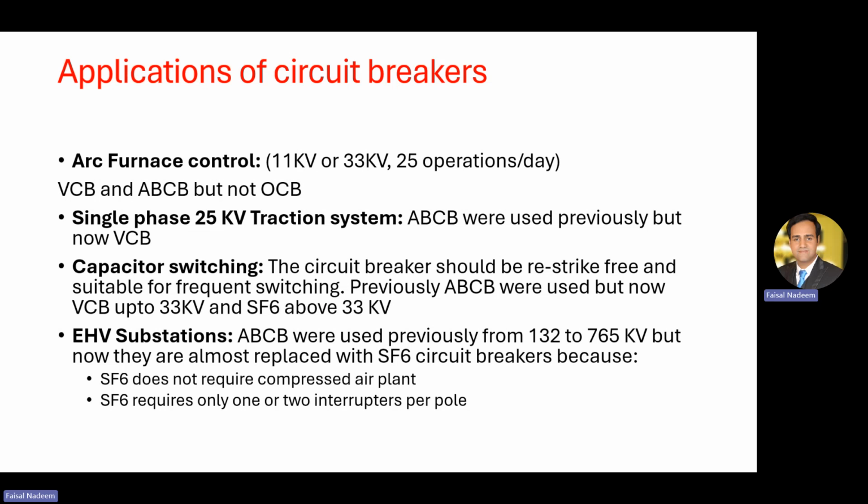And why are vacuum circuit breakers used? Because you know that they perform really well up to 33 kV, and we have here 25 kV systems. Secondly, they are small in size. They take very little space because they are usually installed in the locomotives and the power vans, where we have less space, with modular power system equipment. Because of the small size of the VCB, and because they require less maintenance, VCBs are preferable and they are used in the traction systems as well.